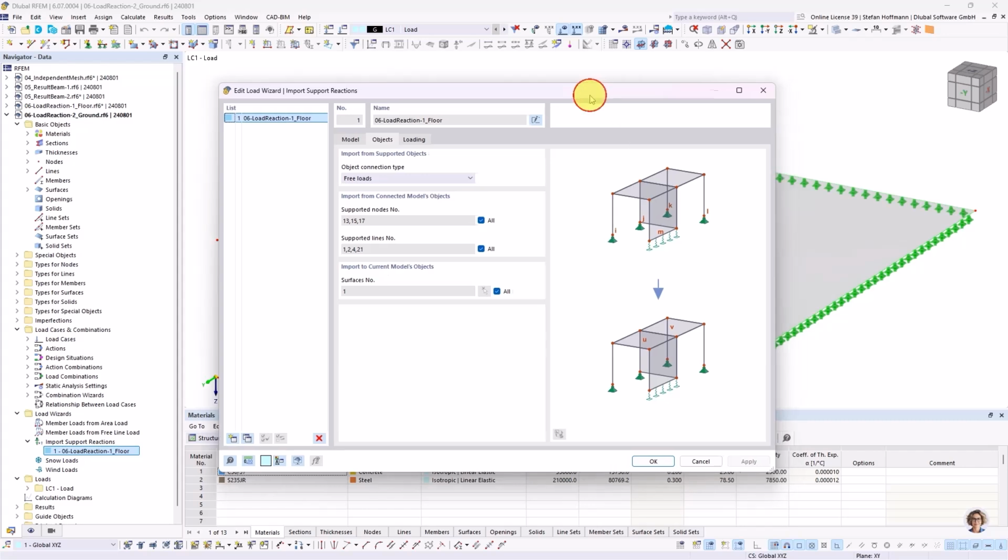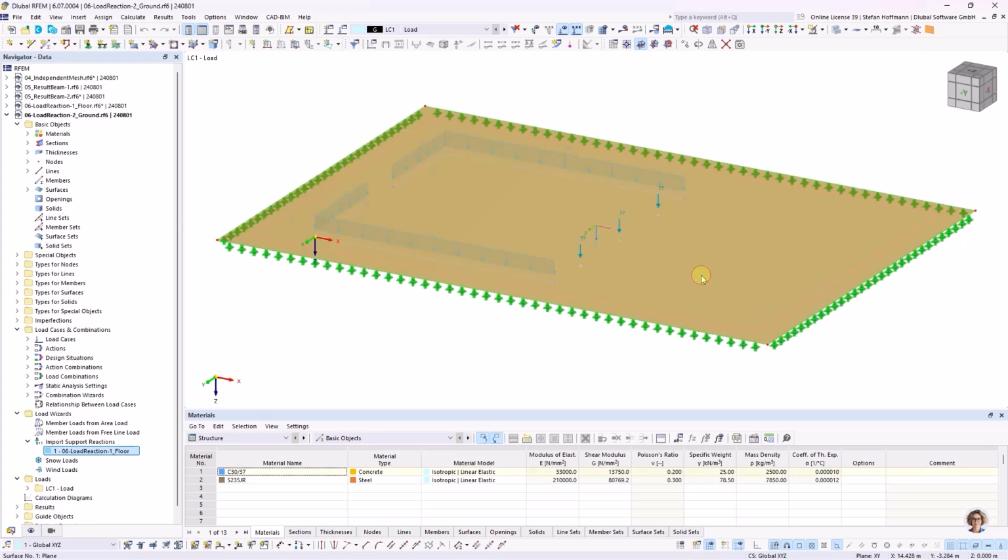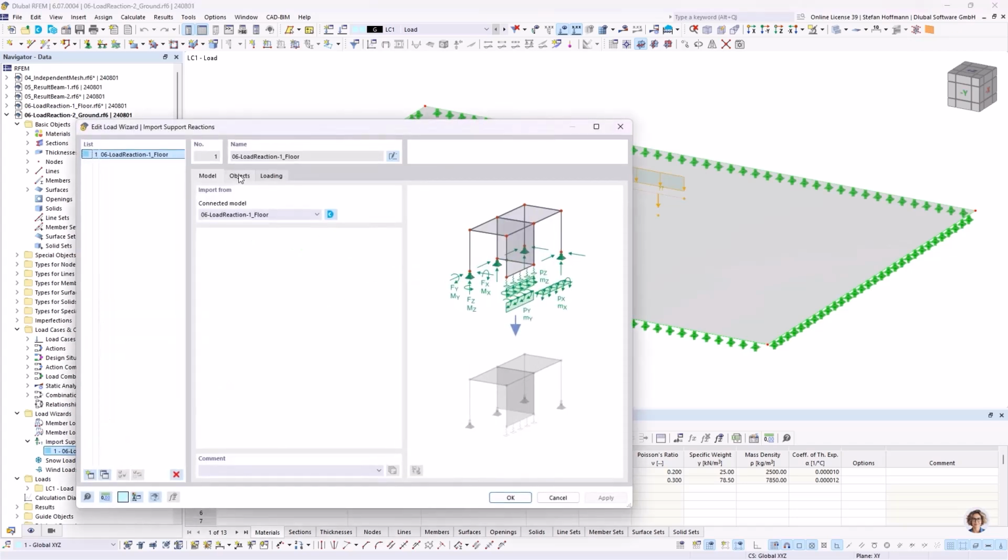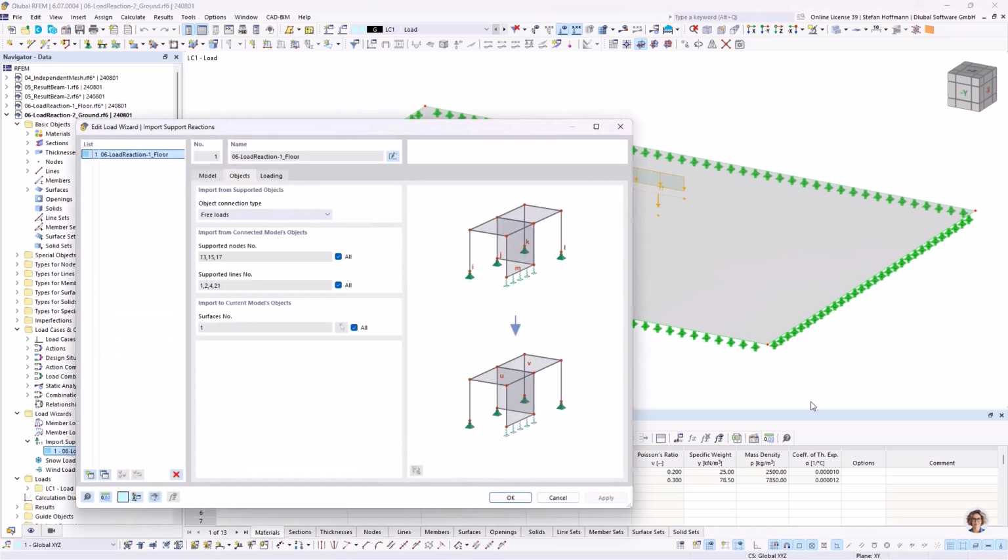the forces. So just imagine if you have a floor lying in here and also define a second surface, all these forces will penetrate into the global Z direction, whatever they can penetrate, and this may double the load if you have the same surface down below. So you would have to think that, of course, if the construct of the part is only standing on one surface, you have to disable the all check and assign these loads to the corresponding surface.